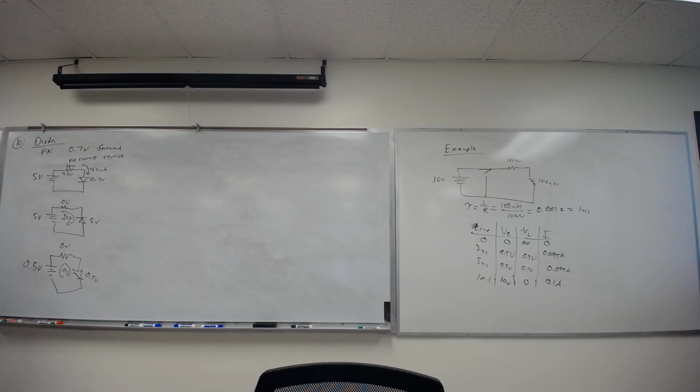Also review the clipping circuits because you did a whole section on that in the lab. Just make sure you understand them. The big thing with the clippers is you want to make sure you're looking at your peak voltages and not your RMS voltages. So you are clipping at 0.7 volts. If you have a 0.7 volt RMS signal, that means it's going up to about 1 volt peak. So chop the top off. That's where you need to know RMS versus peak. Most or everything you'll get will be DC, but the AC part is a valid question.